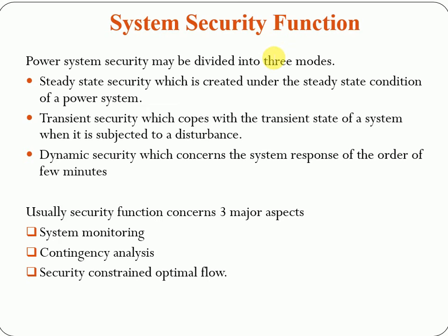Reserve generation means leaving enough reserve generation capacity in case of loss of a generating unit. Transmission capacity means keeping enough transmission capacity to carry the flow that was flowing on the line that suffers an outage.